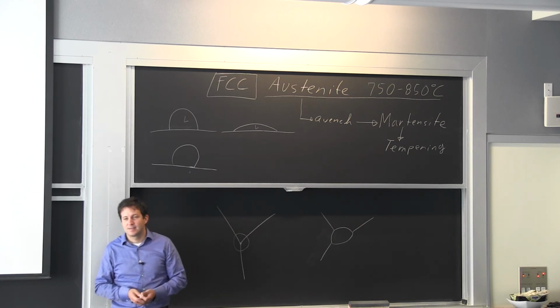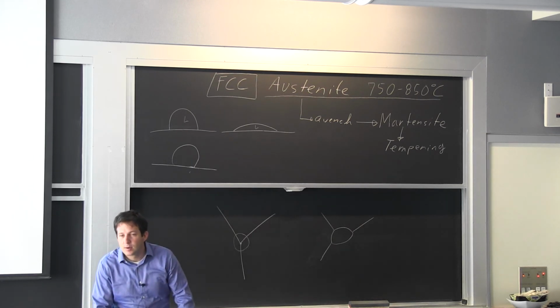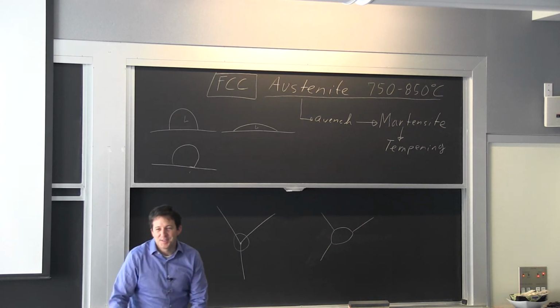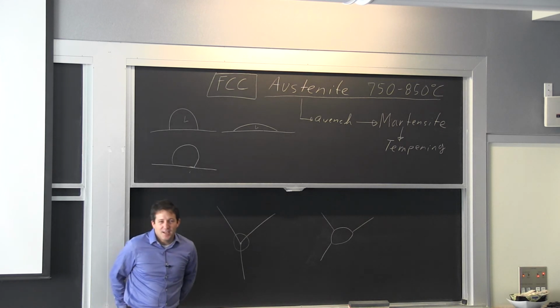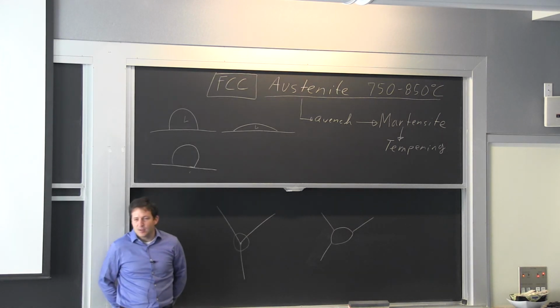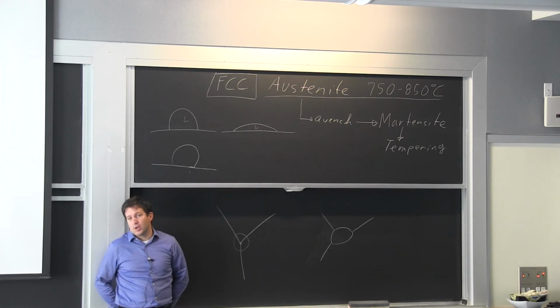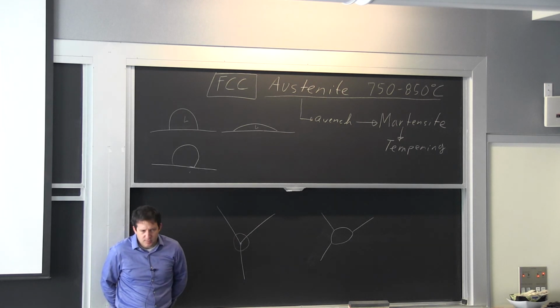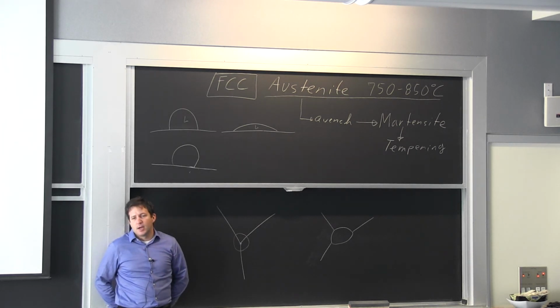Yes? Even on aircraft grade aluminum, like 7075, how hot do you have to get it for it to start noticing that? Oh, now you're testing me. The 7075 can take a little bit more, but I think when you go above boiling, typically with aluminum, you really start wondering if you're going to lose significant strength. If it's the skin, sometimes it's okay, but if it's the primary structure, it's a problem.